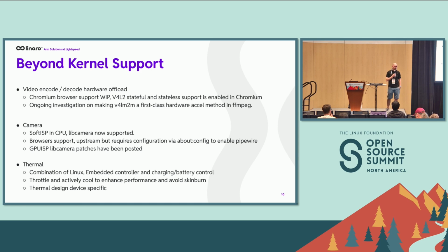We can throttle the GPU. We can set trip points to make sure the device is not resetting or anything like that. But we don't have a good way right now to have a full system view and coordination between Linux, embedded firmware, and charging and so on. So that's definitely something that will need more efforts over time.